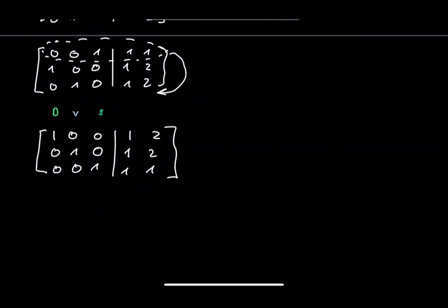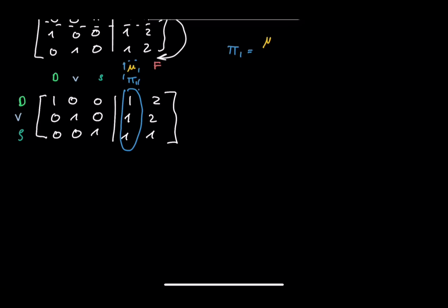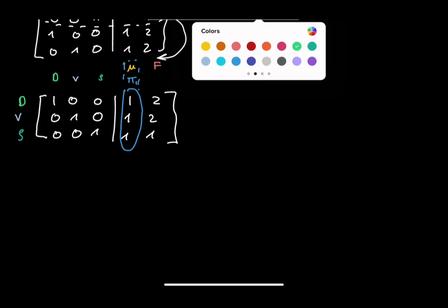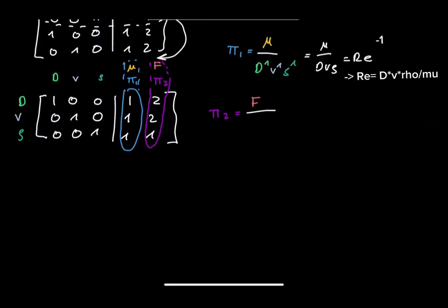From this procedure, we obtain two dimensionless numbers. One is a normalized force, known as the drag coefficient. The other is the Reynolds number, density times velocity times diameter divided by viscosity. This result is not guessed and not memorized. It falls directly out of dimensional consistency.